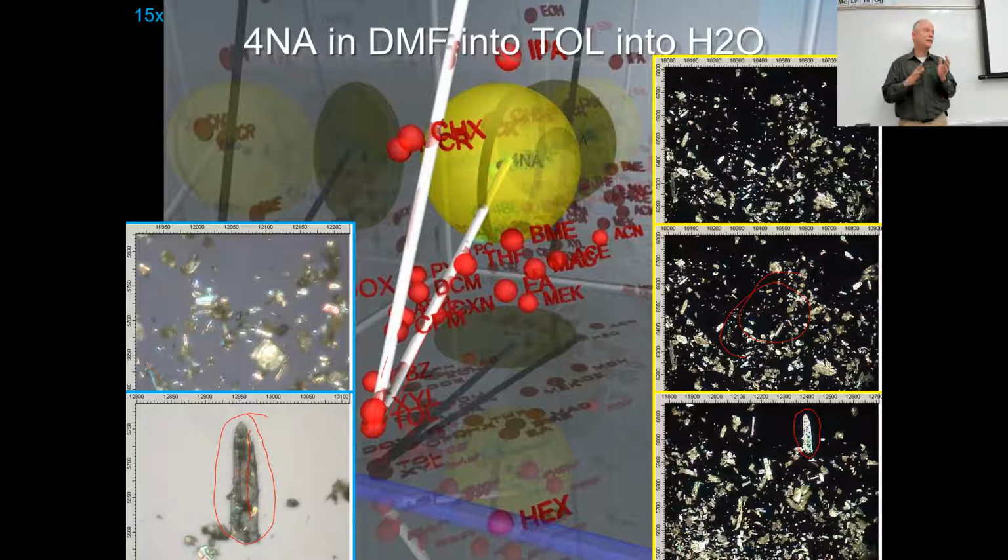If you've got residue on that container, it may have a different behavior. It's very hard to clean scale off the heating element part of that container. If you're doing things in water and you've got calcium deposits, that's going to be a different Hansen solubility profile than clean stainless steel. So you might have a great reaction tank when you first install it, and then it degrades over time, or just the opposite. Maybe it needs to be seasoned a little bit.